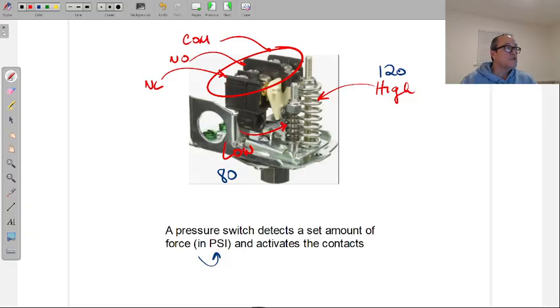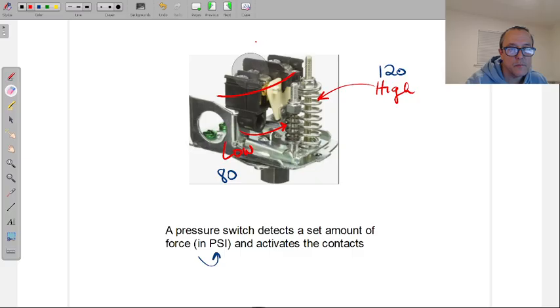A lot of times industrial buildings will have multiple compressors. When you have a pneumatic system that's running a lot of machinery, this now requires more air going into the building, so you're going to have multiple compressors. If not, you'd have one compressor never shutting off all day. So usually buildings have 2, maybe 4 compressors that you cycle throughout the day.